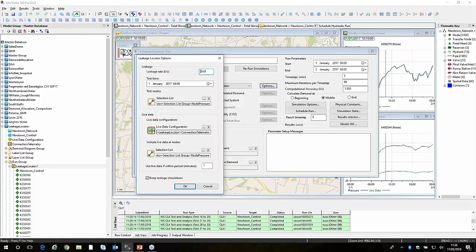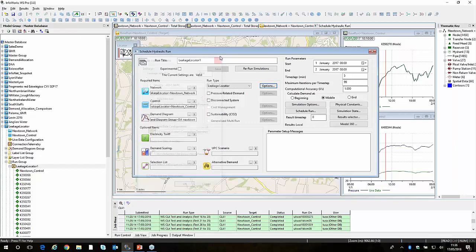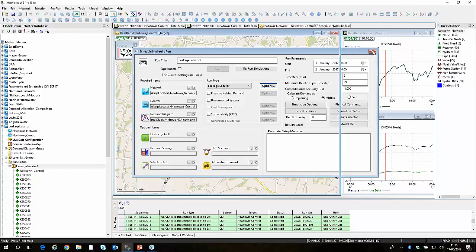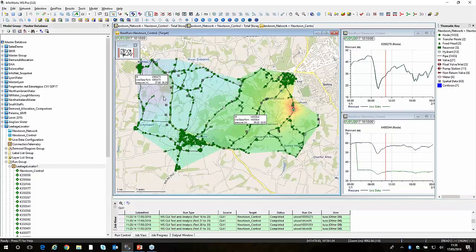And of course, as you can imagine, the closer the value that has been simulated is to what has been observed, the closer we will be to the specific point in the system where the leakage is. So you can see here the result of this critical link analysis shown as a contour again, and you can see here that the pipe burst on my system actually occurred here. So I managed to really cut down into a small number of pipes the exact location of the leakage. But again, this is an ideal condition where the model is very well calibrated.